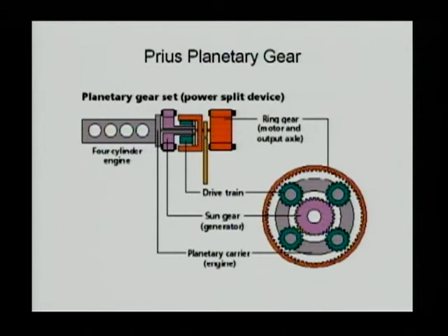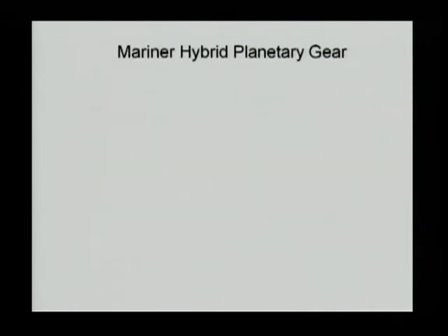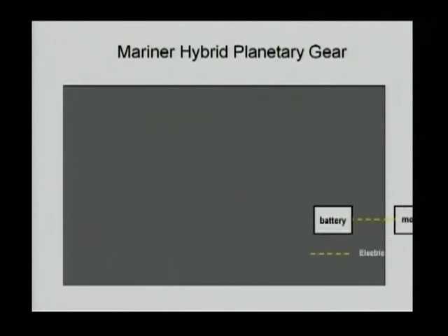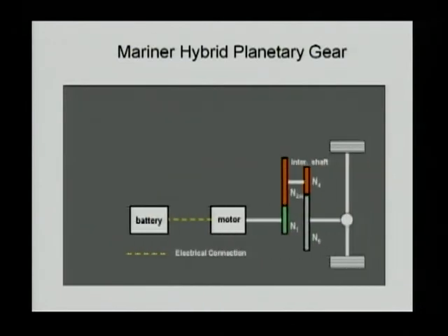So the two inputs are the ring gear and sun gear, and the carrier would summarize the speed. But in this case, it's a power split device, or torque split device in the future, as we refer to it. Therefore, the configuration is different. So let's move to the next slide, which will show you a better explanation of how the system will work.